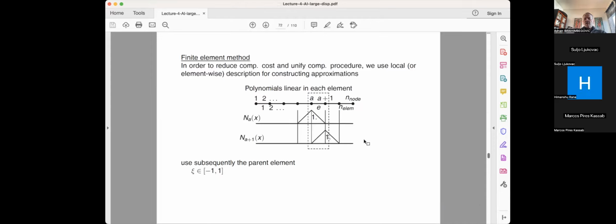So then I can go to a usual finite element discretization. In other words, instead of taking the Galerkin method with a global point of view of how to construct these shape functions, I take an element-wise representation, and I go element by element and obtain the corresponding values of, say, element stiffnesses, internal forces, external forces, and so on and so forth.